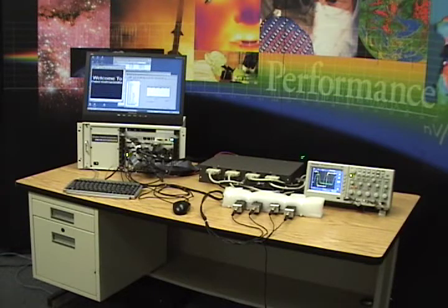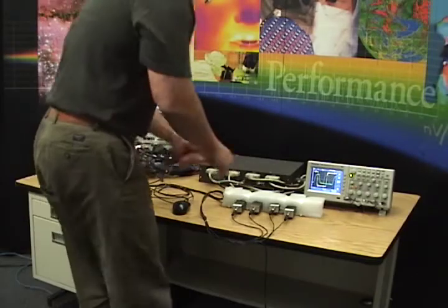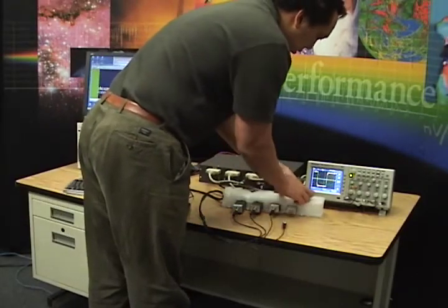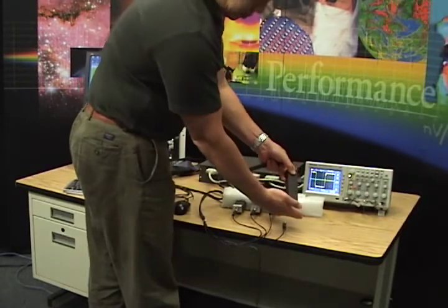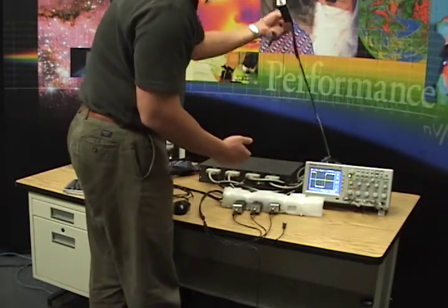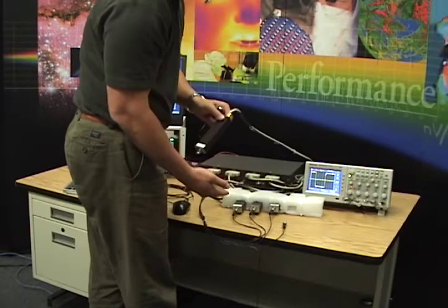The system will also have one or more analog interface modules, or AIMs, which contain gain and filter boards and A to D converter modules. The digitizer boxes also have controls for the external preamplifiers, which apply gain and DC offset correction to the video signals. The preamplifiers are supplied in small aluminum enclosures at the end of 5-foot cables, which allows them to be placed very close to the device under test. This can be critical for ensuring low noise performance.